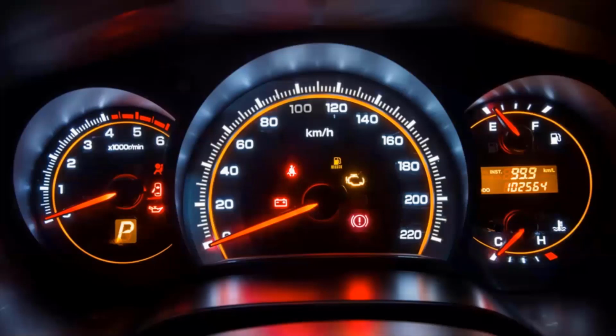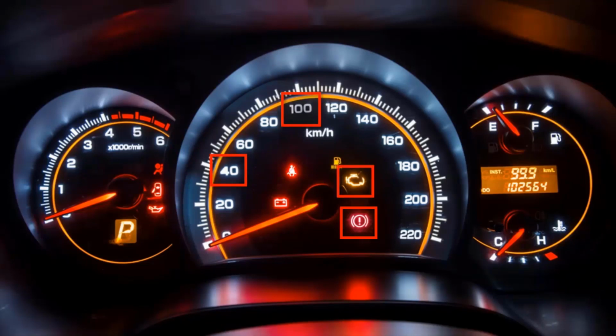So what it seems like, for instance, in the past, looking at this example of an instrument cluster, we've been able to look at the luminance and color of each of these backlit components. For example, we'd be able to determine that this character is too dim and this character is too pink and is a different color. But now we can also look at defects, misalignments, and other laser etched inaccuracies. For example, in this number, there's an etched component missing, and this check engine light has an obvious defect in it.